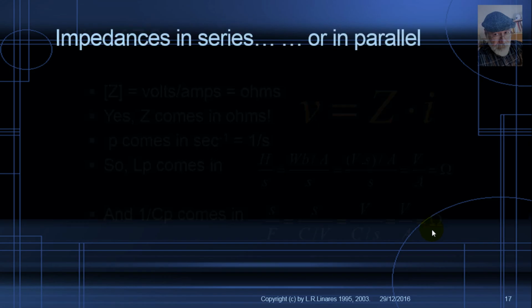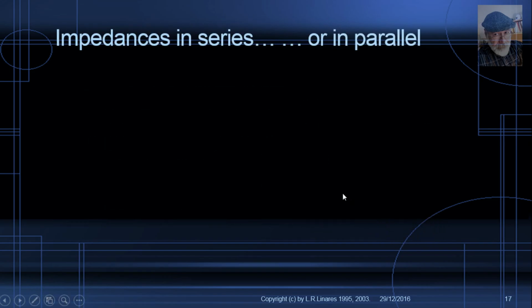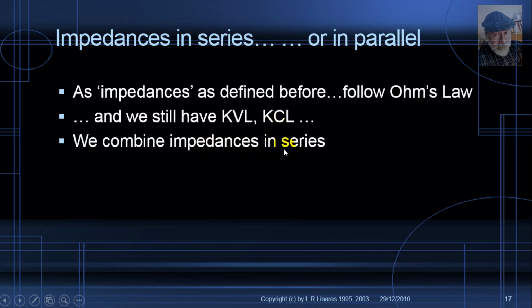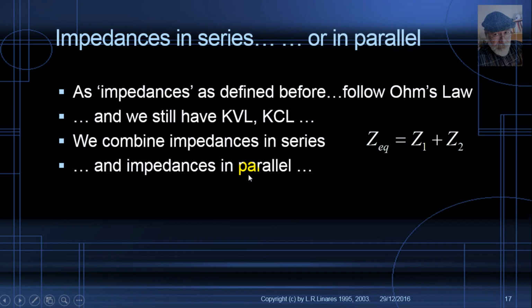Now, let's proceed. Impedances can be combined in series or in parallel. Really? Check it out. Because impedances, the way we've defined them, follow the general form of Ohm's law, and because we never abandoned KVL or KCL, we can simplify impedances in series or in parallel exactly the same way that we simplified resistors in series or in parallel.